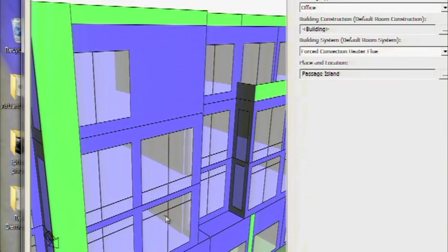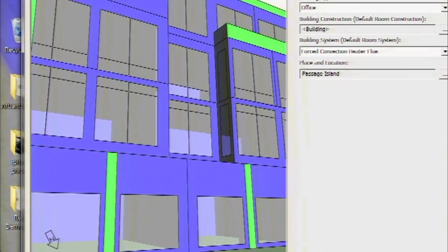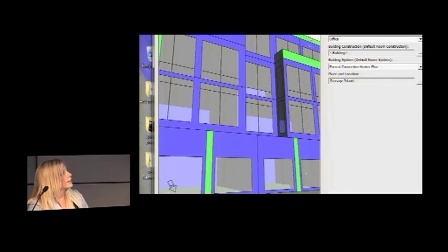If I was going to leave those columns, now I have a room that goes along a few feet, comes in a foot, jogs another foot across, goes out, and then is flat. And it simply has a shading surface across it. So not only is this an inaccurate representation of the room volume, but it's going to cause the calculation to take a lot longer, which is a big problem. Some things like this may be really nominal in the calculation numbers, but if this adds an extra 3 hours to your run, or you have this occurring in 200 places, this really starts to destroy the runtime of your model, and it almost becomes unusable.